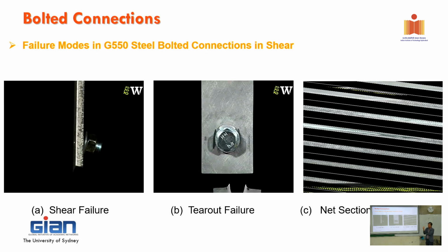So a little bit similar between bearing and tear out. Bearing means that the distance between the edge and the bolt is a little bit further, and it just keeps dragging, and the hole keeps deforming like a slot shape. It just keeps going. That's bearing. But with tear out, when you get close to the edge in here, that whole bit will be gone. So it's tear out like we see in here, okay?